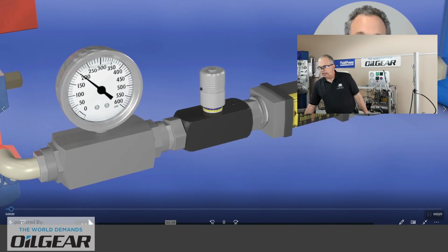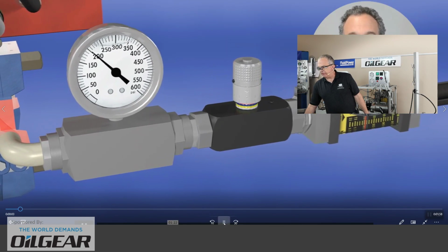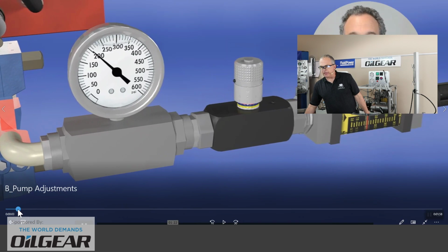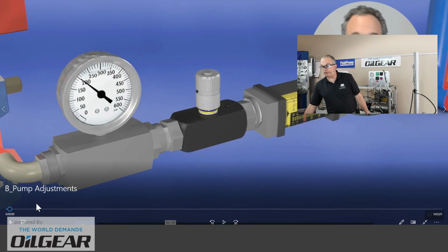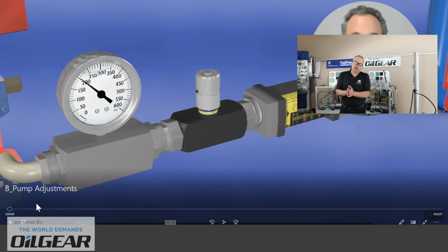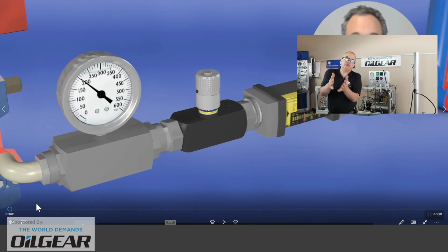Okay, and now let's do a little bit of thinking here about what's happening in the piston pump adjustments that we want to speak about. If you come to a condition in a hydraulic system where the cylinder loading or perhaps the hydraulic motors are overloaded, or perhaps we're in a condition where directional valves have closed and blocked the primary flow of pump fluid through the system, any of those conditions basically are an example of an overload condition where the pressure would run away to much too high a level.